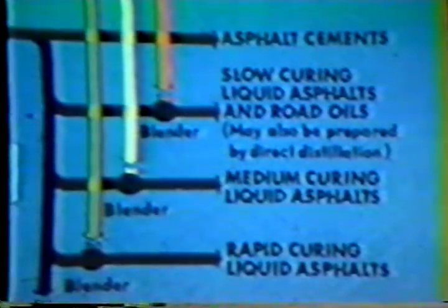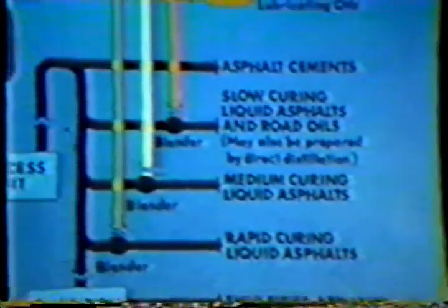Now there's another way of liquefying asphalts, and that's by emulsifying it with water and an emulsifying agent, generally soap. And this is a special procedure which we'll cover in a little bit of detail after we get through with a little more discussion about cutbacks.